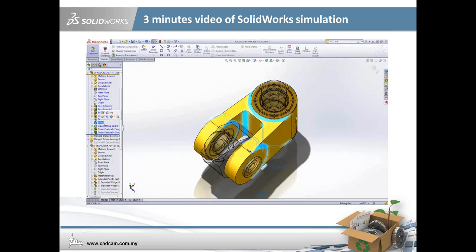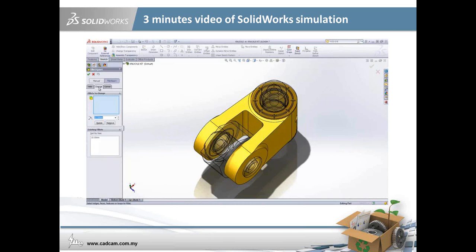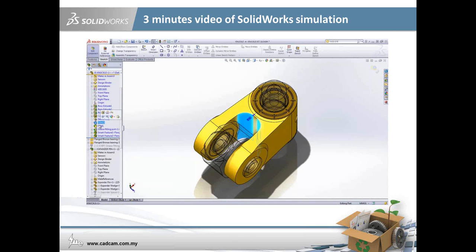But remember, when we created the fillet, it included a bunch of edges that should stay the same. Well, this isn't a problem. With the fillet expert, it's easy to change individual fillets without destroying others. We'll choose these two fillets and resize them to 30 millimeters. SolidWorks separates them from the others, preserving our design intent.